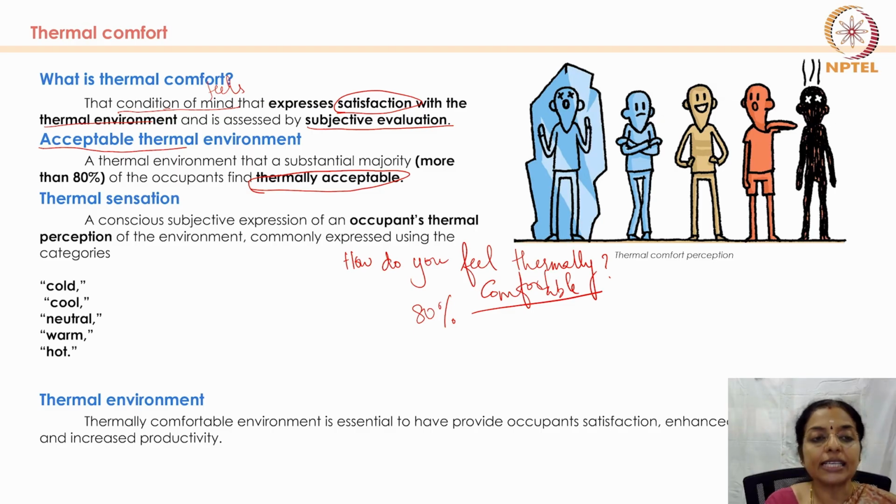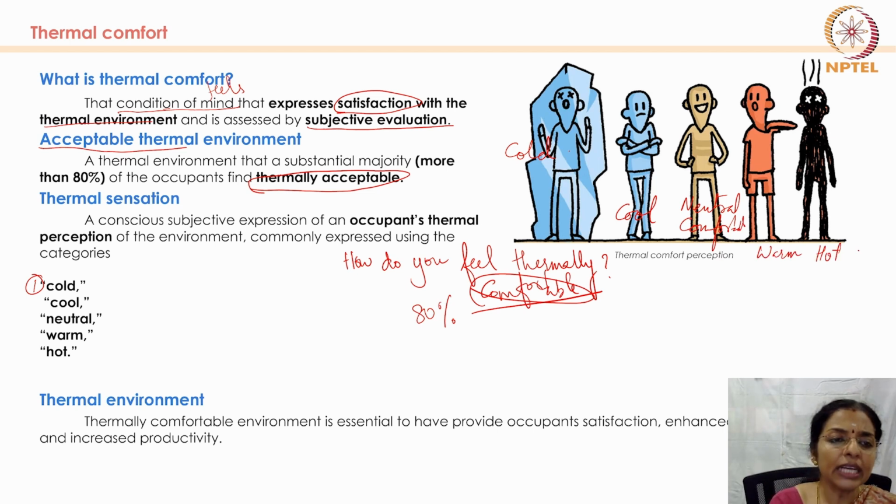So how do you assess thermal sensation? How do you feel? How do you answer that question? If it is comfortable, well and good, comfortable. If not, then it can be either cold, or it can be cool, or it can be neutral. Okay, I'm okay with this. Or we can even say comfortable, or it can be warm, or it can be hot. This is 5 ways of